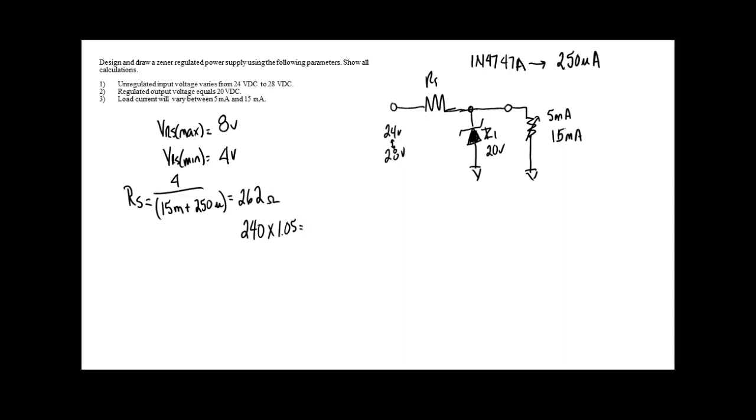I don't know. Brandy looked it up. Do we have a 250? We do, okay. We're looking at the 5% chart. And believe it or not, I need to take the 10% off there. You can't even get 10% resistors anymore. Believe that or not. About the worst percentage you can get is 5%, and then it goes down from that.